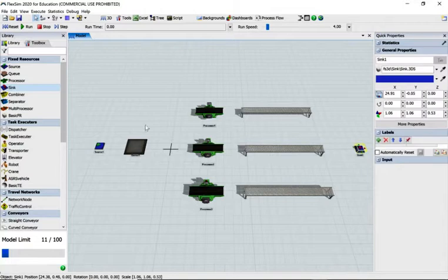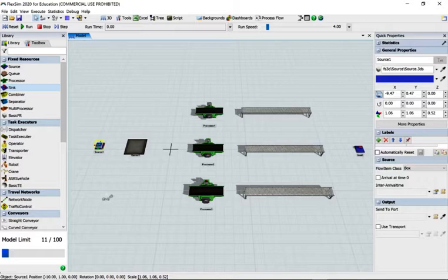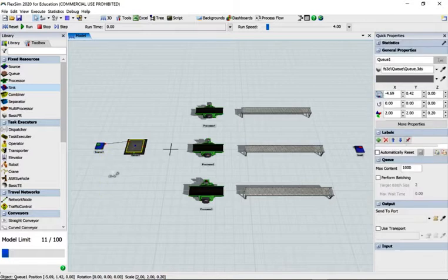So we need to join all these up, and it's very, very important that you get the directions right. So we want a connection to go from the source to the queue, so it's left to right. Our model has been created. So hold down the A key, so it changes to this little chain. Click on source, get the yellow elastic band and click on queue.